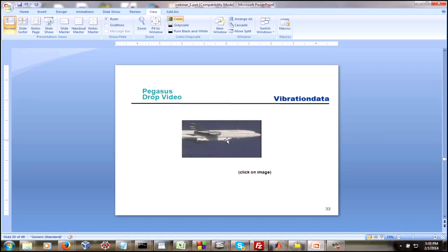It's actually slightly bowing downward due to the effects of gravity. And that places an initial strain energy or initial displacement on the Pegasus launch vehicle. And when Pegasus is suddenly released, then that initial strain or initial potential energy gets converted to kinetic energy, and that conversion takes place at the natural frequency of Pegasus.